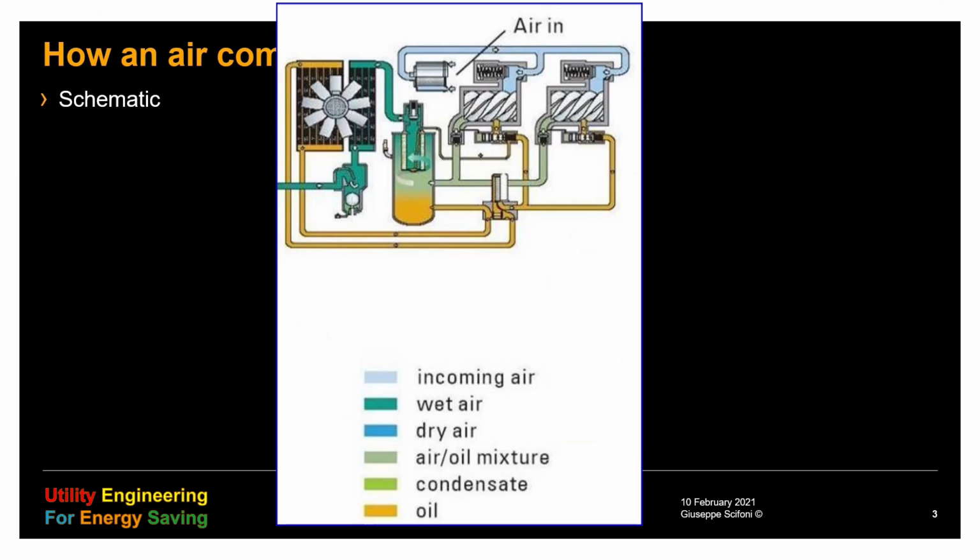The screw machine consists of a couple of screws which are turning together and opposite. After the compression, the air is filtered and the oil is flowing back, first into a heat exchanger, it's cooled down and then comes back to the screw housing. Differently from the centrifugal, the oil screw machine is only one stage and the air stream is mixed together with oil. There also exist water-lubricated screws as well as non-lubricated ones.